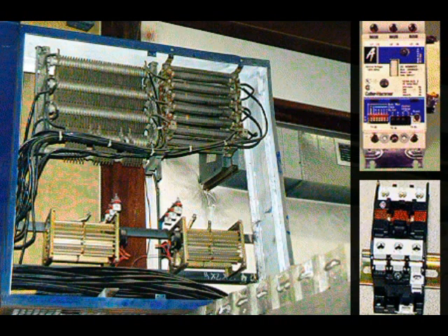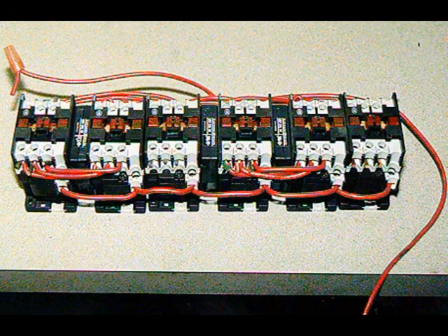Motor starters. All electric motors, except very small ones such as chemical feed pumps, are equipped with starters. These starters can be either full voltage or reduced voltage. Starters are used because motors draw much more current when they are starting and gaining speed than when they are at full speed. Reduced voltage starters prevent the load from coming on until the amperage is low enough.